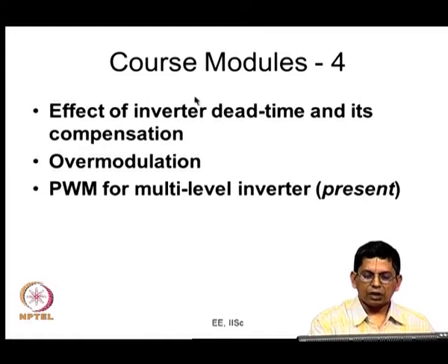Here in a 3 level inverter you have 2 pairs of complementary devices, and again the outgoing device should be switched off first and then the incoming devices later. Now, you can actually do this dead time analysis for the 3 level case also, but that is something that we are not going to really look at. Again we went in for over modulation.